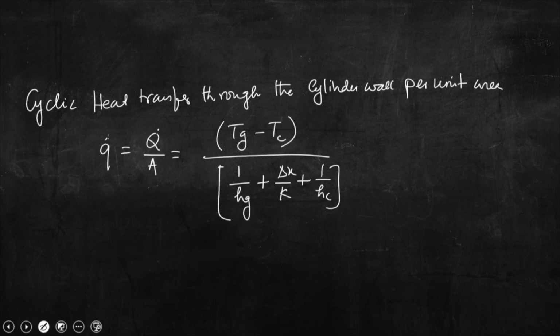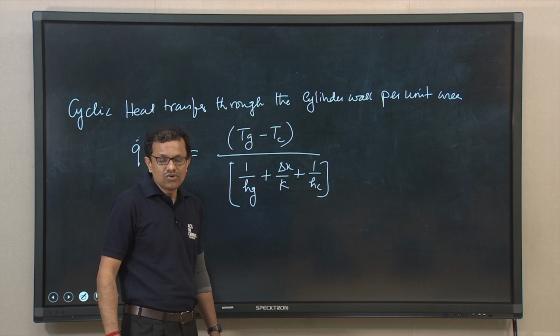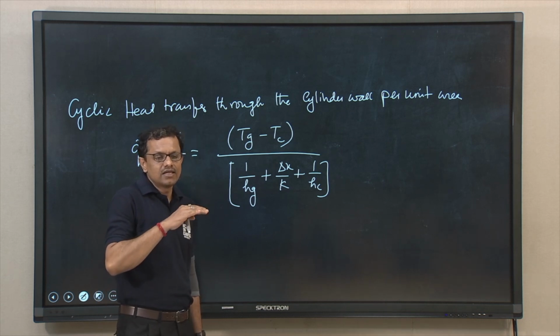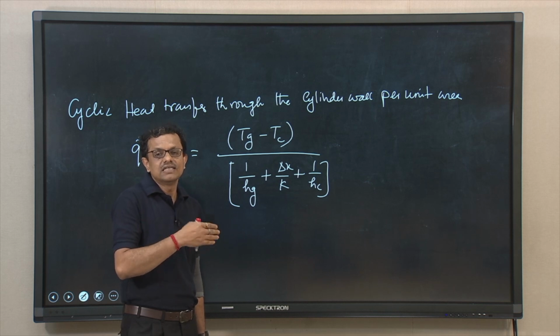Now, I would like to discuss a few important things. Here T g, would we like to consider T g constant? No, T g will vary across the space of the combustion chamber, and it will also vary over an engine cycle.